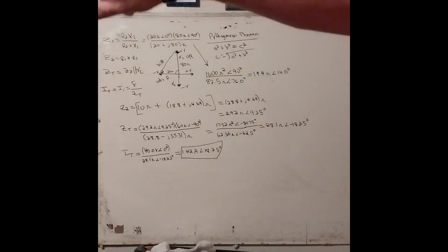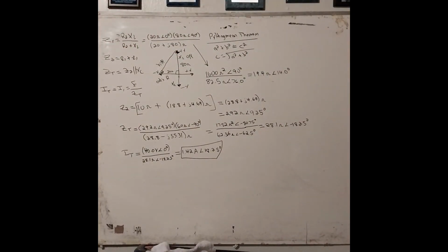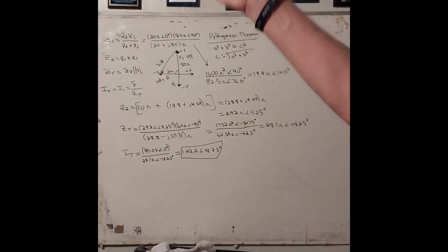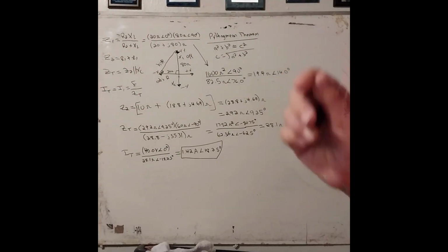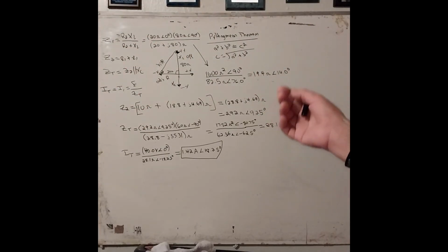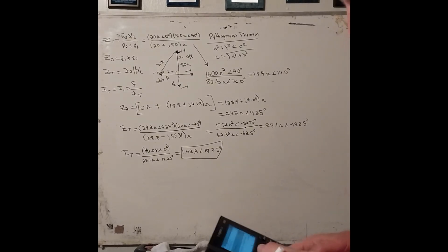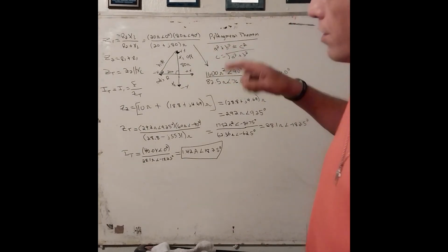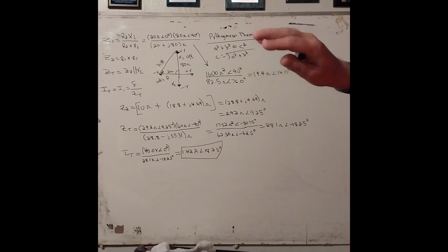Yeah, total current flowing through the total circuit makes 40 volts, and then 40 volts divided by that gives that current. Those two currents add to 1.42 amps. So the current flowing through the capacitor is actually 54 milliamps, and 1.37 amps is flowing through Z sub 2,